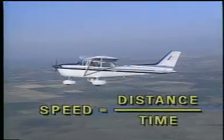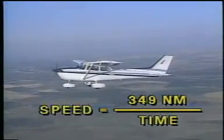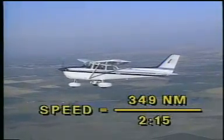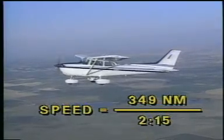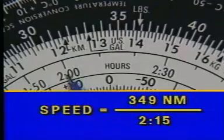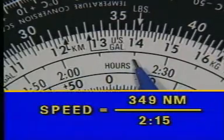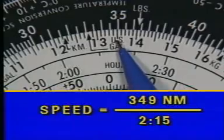You determine the ground speed of your aircraft in a similar manner. If you've traveled 349 miles in 2 hours and 15 minutes, what is your ground speed? First, locate the time for this flight. Since 2 hours and 15 minutes is not marked on the C scale, you should use the time in minutes, 135 on the B scale.